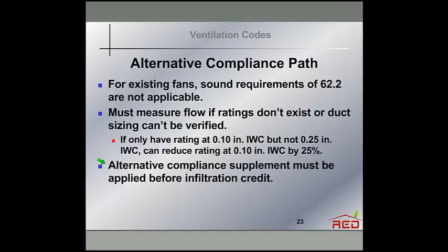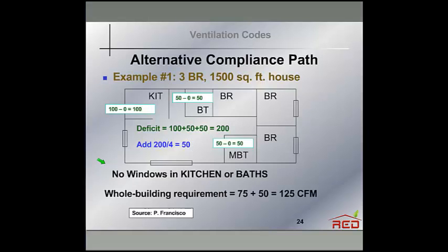If you happen to be installing an inline fan, you might install a fan up in the attic and it serves 2 bathrooms, for example. Inline fans do not have zone ratings because they are installed remotely, and that's fine under the ASHRAE 62.2 standard.